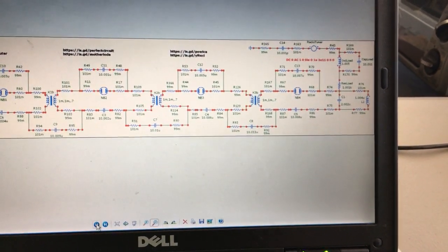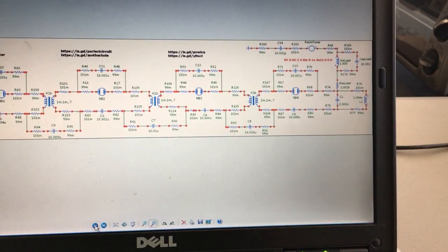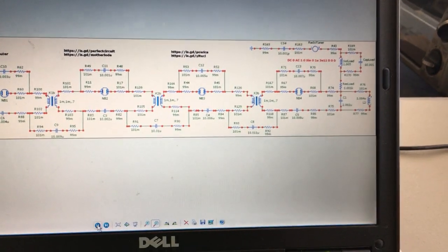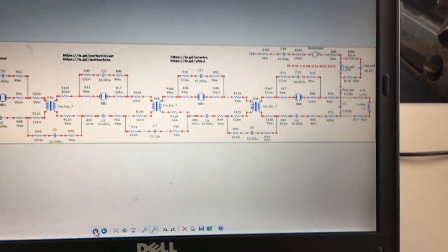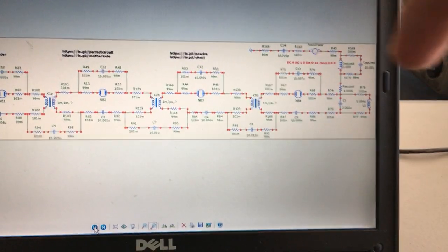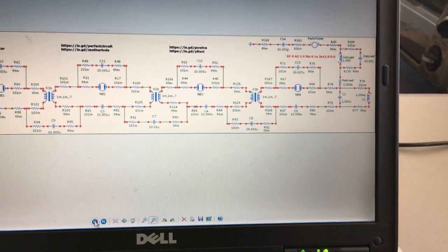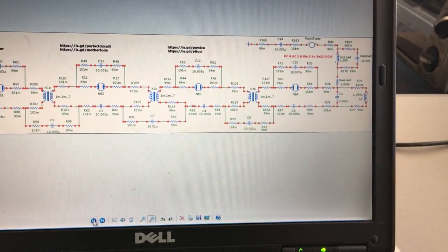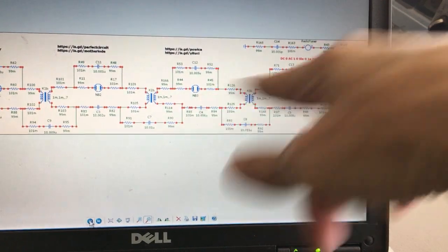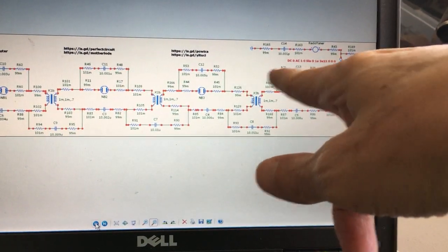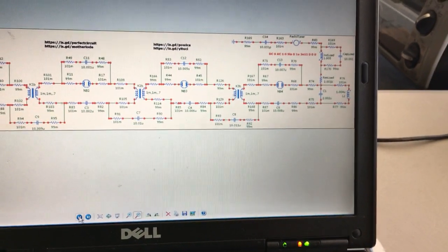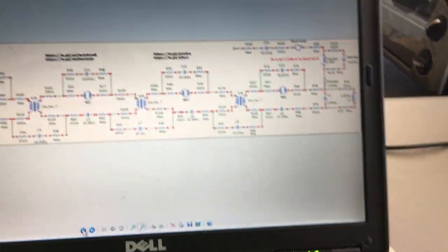And I don't know, that's going to be a whole other mess, knowing how to fine-tune it, because up front I may just be able to turn this thing on and off, and at least that'll be something. Because if I use a timer clock to change the varactor to cause the circuit to come on and off within a certain duty cycle, I can fake fine-tuning or throttling the output of this circuit by how much percentage of each cycle time it's on versus off. That's pulse width modulation, basically. So there you go. Maybe that's how we regulate this thing.